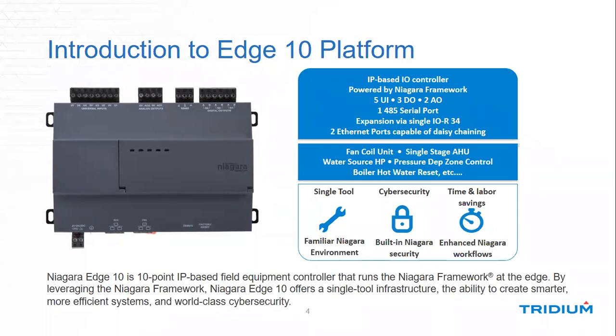Cybersecurity. With the onset of these IP-based controllers, cybersecurity is going to be a major talking point in the industry. And it's very important because with these IP-based controllers, you're not hooked up to a traditional quote-unquote offline network that's just kind of hidden in your building by obscurity. Now you could be connected to the IT network, you could have a specific OT network, but either way, these types of devices are probably a lot more accessible. So all of the focus that we put on cybersecurity here at Tridium with Niagara goes into these boxes as well, just like any other Niagara version.